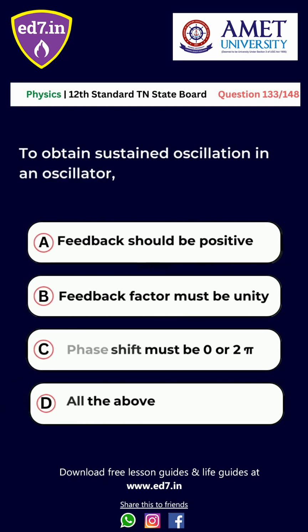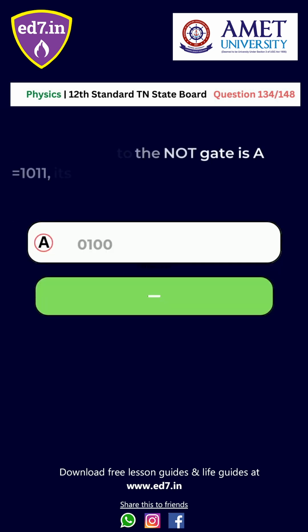Question number 133. To obtain sustained oscillation in an oscillator, option A, feedback should be positive. B, feedback factor must be unity. C, phase shift must be 0 or 2π. D, all the above. Right answer is option D, all the above. Question number 134.